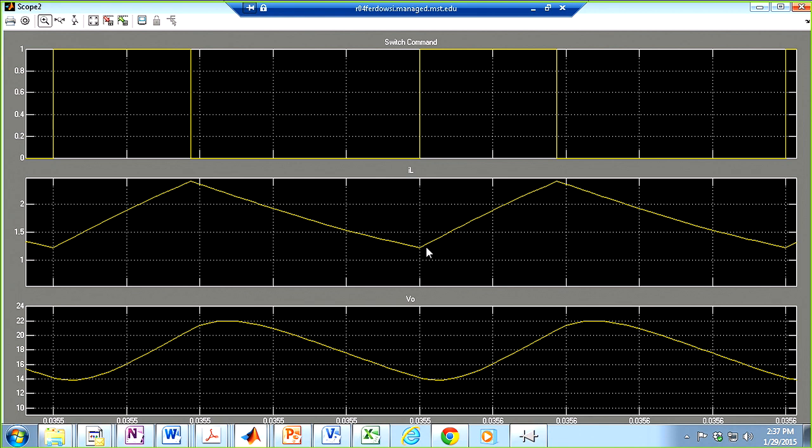Other questions? Yes. Will our continuous or discontinuous mode depend upon the D that we take? For example, say a buck converter, V output by V input is D. So if you take below 0.1 or above 0.9, will it be a... Okay, good point. You're right. The question is, what about the effect of the duty cycle on going to discontinuous conduction mode or not? So let's look at that. You're right. These will also...